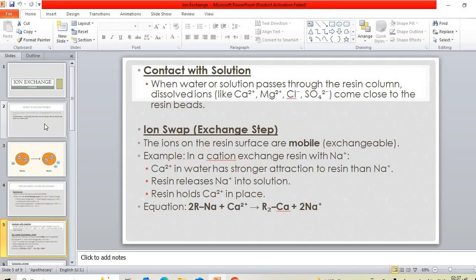And then we go to the contact with the solution, and most likely it is water because it is widely used in water treatment plants and even in refineries and utilities to get rid of these ions. In case you work in the oil and gas sector and you need a boiler, the boiler needs to get rid of, for example, calcium plus 2 and magnesium plus 2, because those are responsible for hardening the water, and also other ions that could cause scaling on the boiler wall, which lowers the heat transfer efficiency, which is the core of the boiler itself.